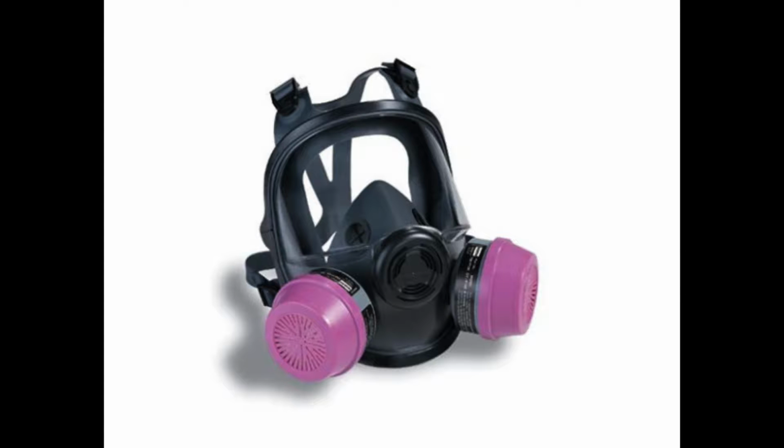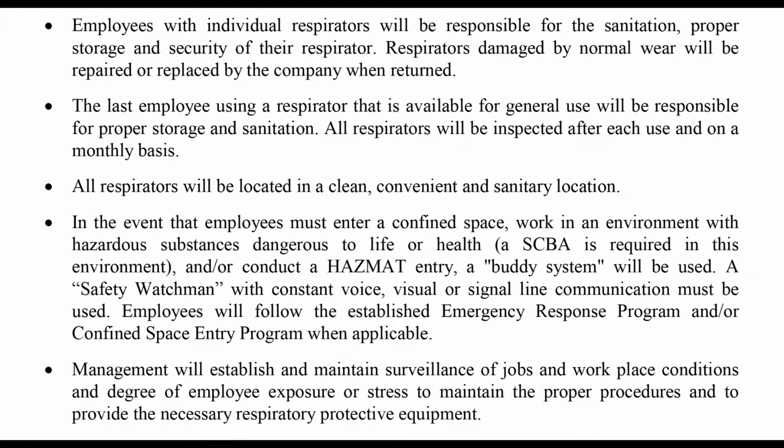Only SCBAs will be used in oxygen-deficient environments, in environments with an unknown hazardous substance or unknown quantity of a known hazardous substance, or in any environment that is determined immediately dangerous to life or health, IDLH. Employees with individual respirators will be responsible for the sanitation, proper storage, and security of their respirator. Respirators damaged by normal wear will be repaired or replaced by the company when returned.